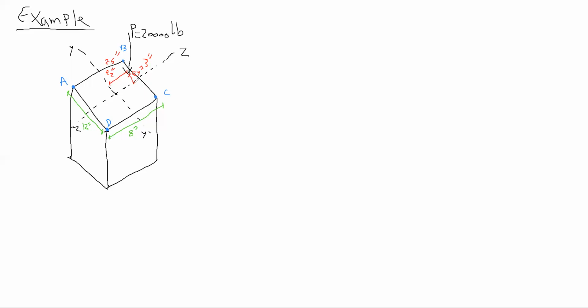And now I want to start to derive the figure, and I want to ask you to help me with the index of the moment or something like that, right? Just follow me. So again, let me draw here again. I want to move the force to the middle, because these forces make moments. You have two moments and one compressive force. Every time we should apply the moment and the force at the center of the shape. For a T-shape, you should find the center, but here it is easy because we know the center of the rectangle is in the middle, right?